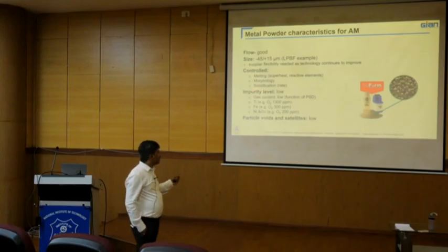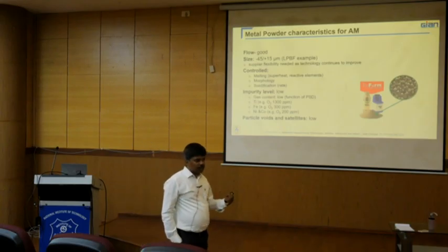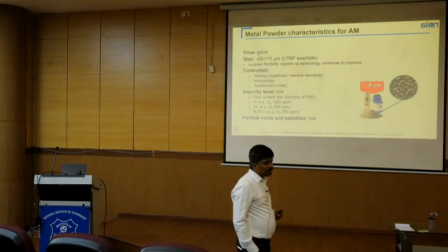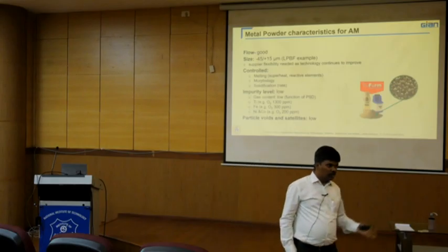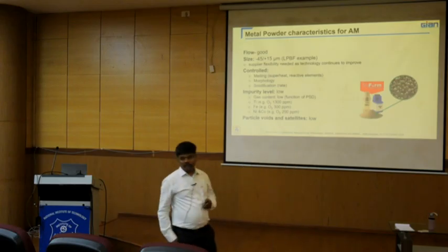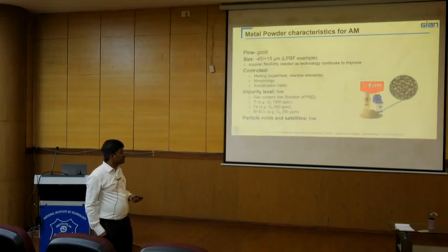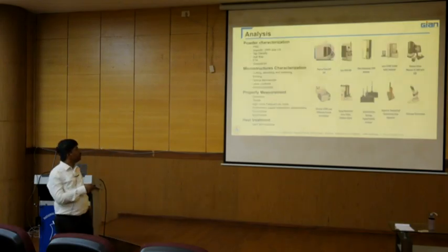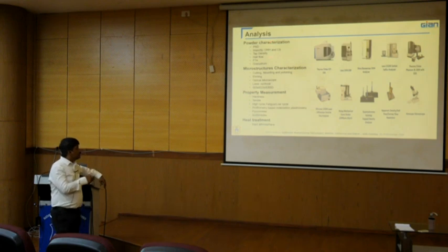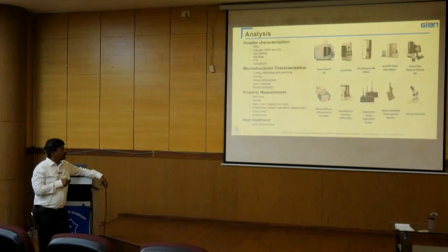Because if you do not consider these things, then ultimately you cannot justify whether the defects or low mechanical properties are caused by your powders or by your process conditions. That is why we need to buy highly qualified powders by analyzing all these process conditions and characterization aspects. I told you powder characterization can be done by particle size distribution, impurity with ONH or CS, or with tap density, Hall flowmeters, FT4, granudrum.